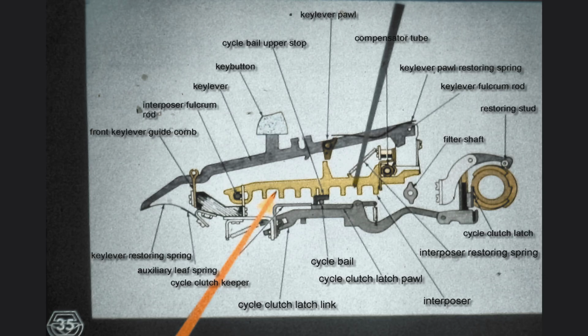However, since the -5 latch is also pulled toward the front, we release 5 increments of negative rotation for the type element. If we actually perform this on the machine, it turns out that the number 1, or the bracket, would print, since it needs this particular selection in order to be placed into the correct position for printing. That is how the machine performs character selection. Before you continue, be sure that you can explain the operation of this section of the input mechanism. Do not hesitate to review this material while you check out these statements on your machine.